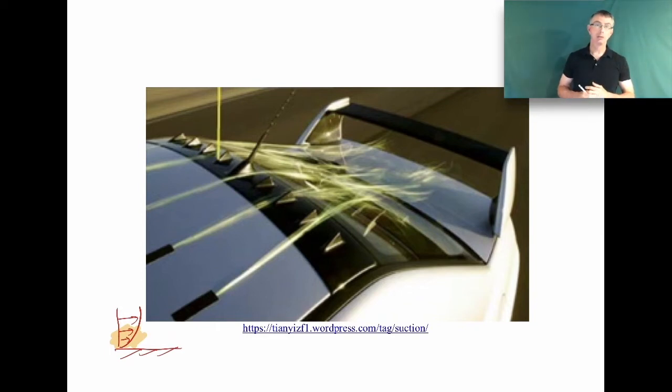And this low momentum air, it turns out, as we'll see in a couple of lectures, doesn't flow very well into higher pressure regions. So if we had a high pressure in this region, then this flow won't go into that high pressure region very well. You can imagine that if you have small amount of momentum here and you have pressure pushing back on it, that fluid won't want to move into that region very easily. High momentum fluid, however, may be able to push further into that high pressure region just from its momentum, right? It has a high momentum, it can push further against that pressure gradient. But low momentum air doesn't very well.